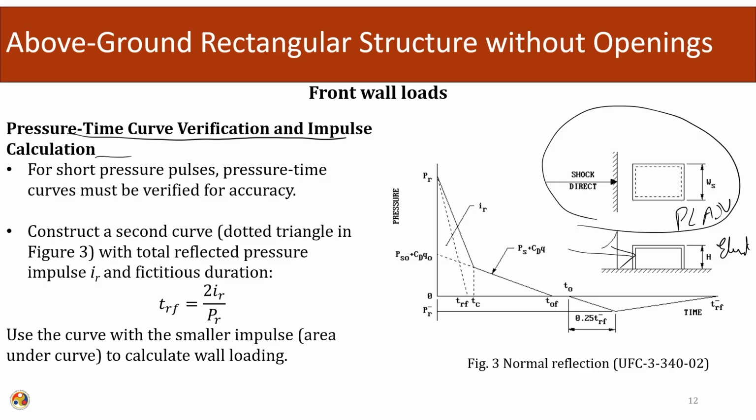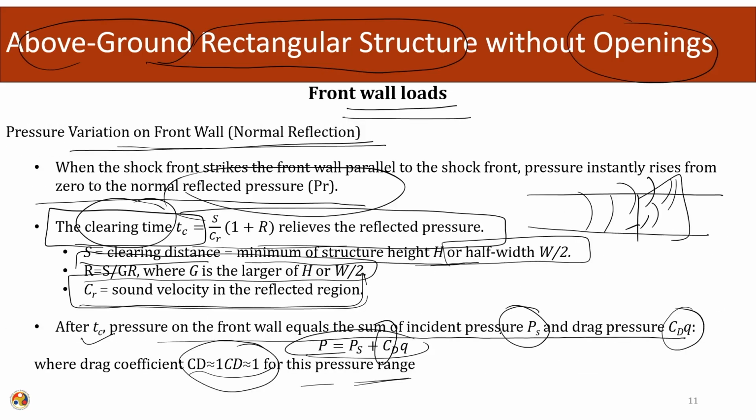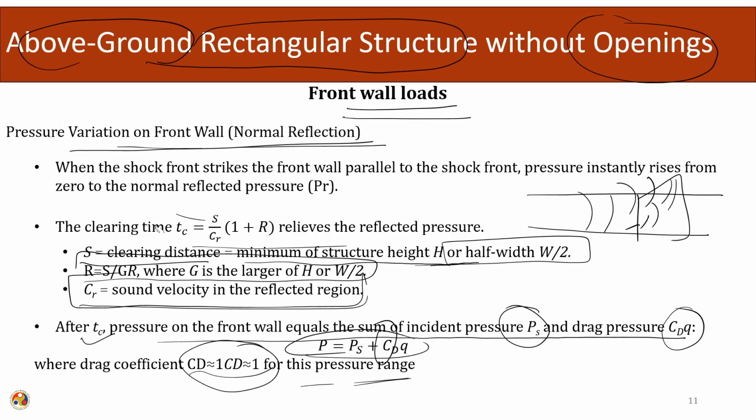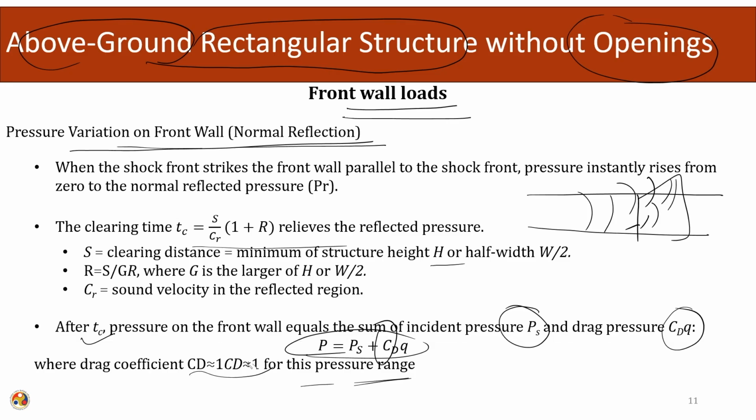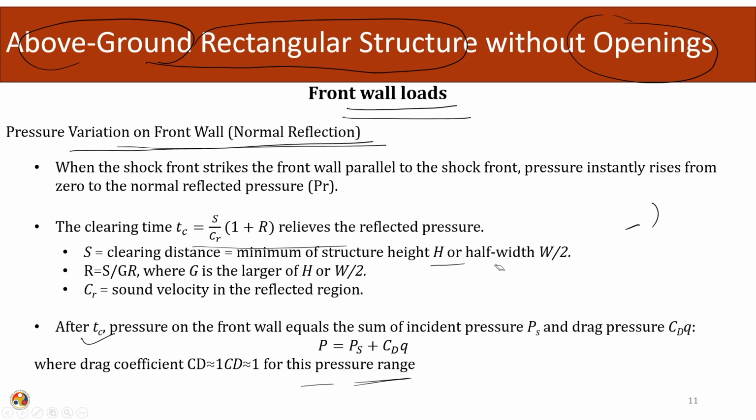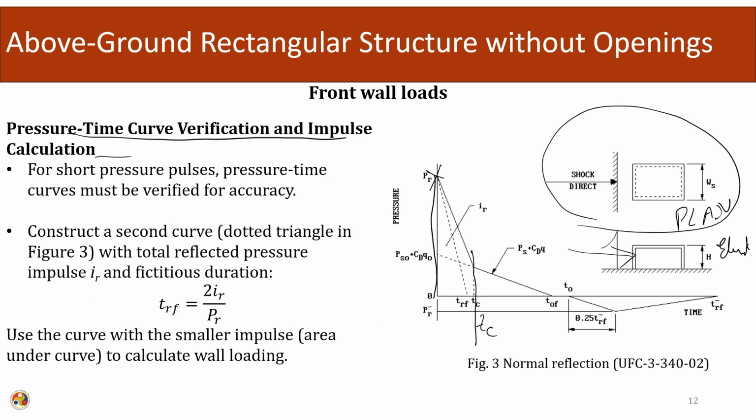Instantly we will see the reflected pressure, and the reflected pressure will be applied till the clearing time Tc, as we have seen here. After the clearing time Tc, the reflected pressure is removed, and there will be incident pressure and the drag pressure.